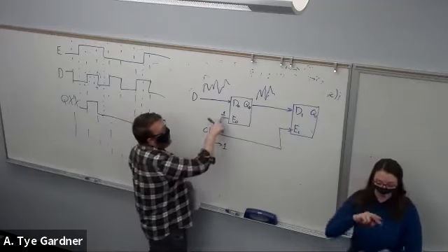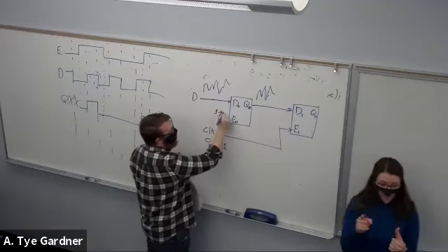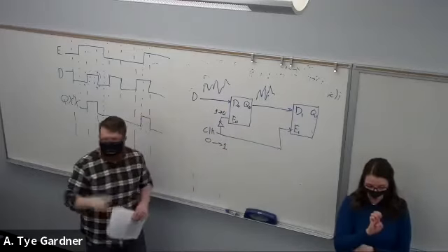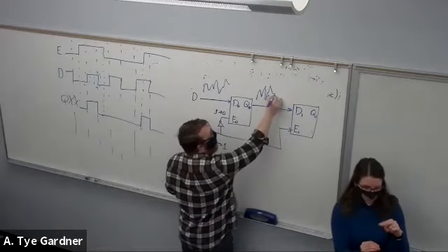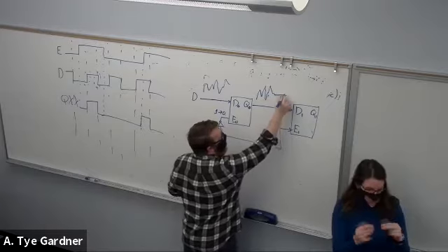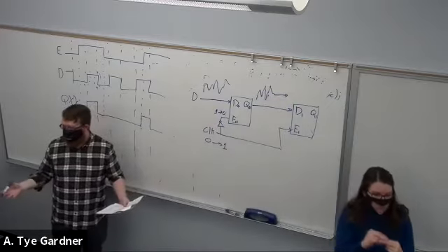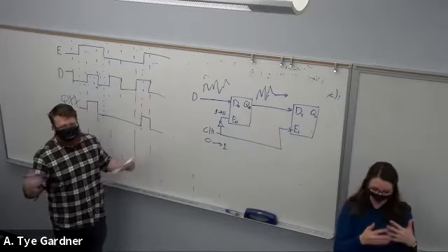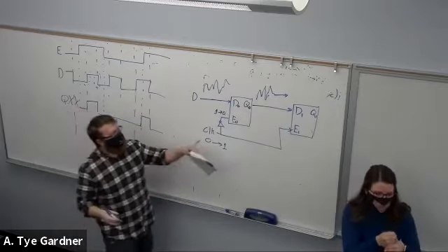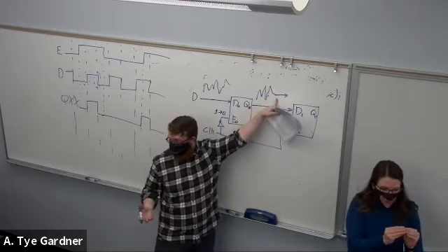That means the first enable drops from 1 to 0. It's no longer on. That means the output of that latch latches on to whatever that value was, a 0 or a 1, right? I'm pretending like it has lots of values. Really, it's a 0 or 1, but I just want to illustrate. It's just going to take that last point and hold on to it.